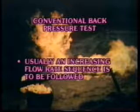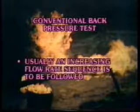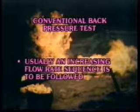This pressure is recorded. The well is then produced for a series of at least 4 stabilized flow rates, and stabilized pressures recorded for each. The shut-in time between flow rates should be minimized. An increasing flow rate sequence is to be used unless a high liquid ratio well or unusual temperature conditions prevail. The lowest rate should be sufficient to keep the wellbore clean. Good data spread is required. Wellhead flowing pressure should not be less than 95% of the well shut-in pressure at the lowest rate, and not more than 75% at the highest flow rate.